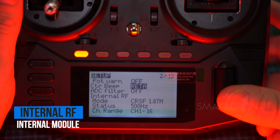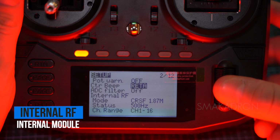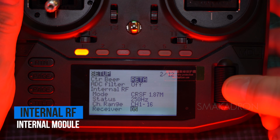Channel range. The channels that will be used for communication. In the CRSF settings, the channel range parameter allows you to define which channels will be used for communication between the transmitter and receiver. If the value is set to CH1 to 16, it means that channels 1 through 16 will be active and used for signal transmission. This range includes the first 16 communication channels that can be configured for various functions, such as controlling motors, ailerons, elevator, rudder, and other auxiliary functions. You can configure each channel separately according to your needs, assigning them appropriate functions and values. But I recommend leaving it as is.